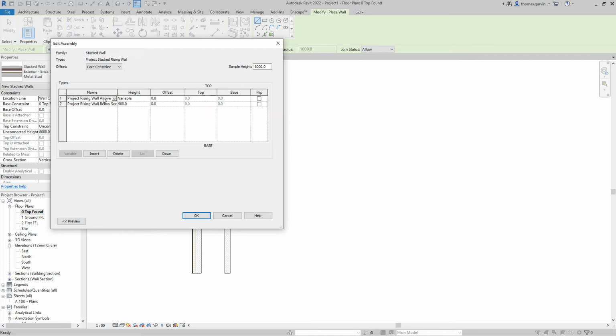Now the above section has the insulation on it. We want that to be fixed to it's lapping with the floor insulation, so we know what that dimension is, and we should have maybe thermal blocks inside it. So we want that fixed. So it's either maybe 450 or 675. It's a modular amount with the height of bricks. So therefore we want that fixed, and we want the wall section below to be variable, so to stretch with the height of the wall.